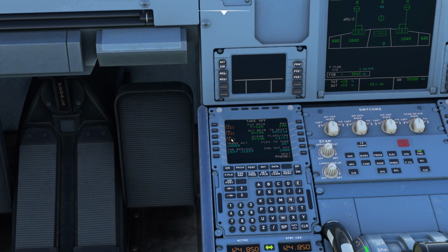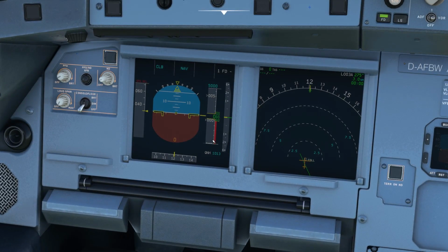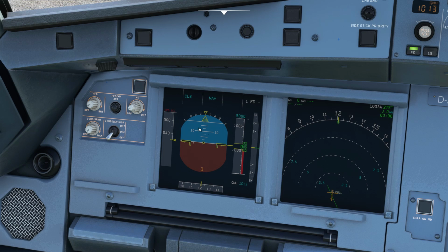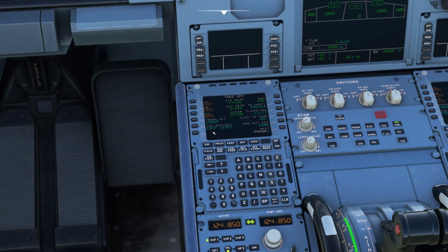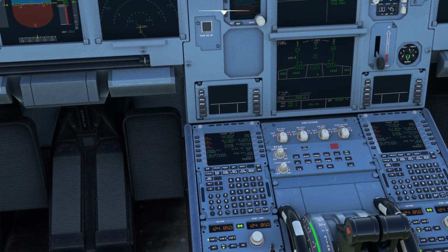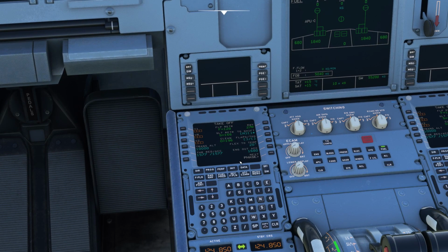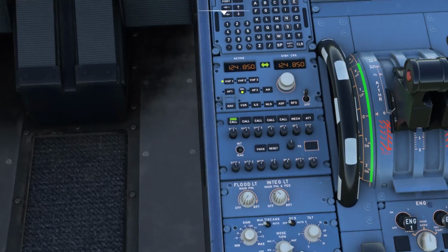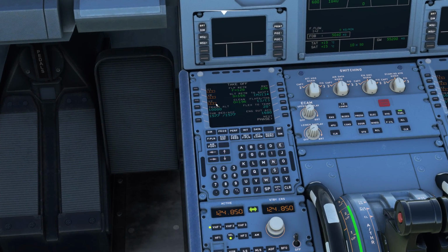First of all, these are important. These are the speeds that the aircraft is going to display on the screens to tell you where you want to rotate and when you're going past your V1 speed as well. What you have to do to get to this point is enter all the other information you need first. So I'm going to enter information about the flaps, the temperature in the area, so the flaps takeoff, which is a flex to temp, and I'm then going to enter transition altitude for the QNH, which is this here, and then I'm going to look at entering these speeds. The speeds are worked out for you, so this is why you have to do this first. You can just enter the speeds automatically, but you may get V speeds disagree, in which case you have to change them anyway. So let's have a look.